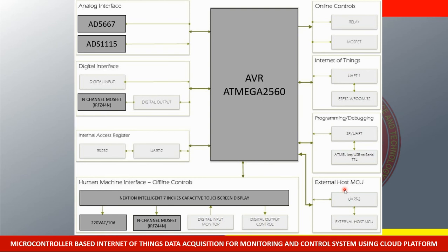We are going to utilize the pulse width modulation of our microcontroller, so it makes sense to use an N-channel MOSFET, because we utilize the PWM. What that means, let's leave for a future discussion. So, for our online controls, we have the N-channel MOSFET.